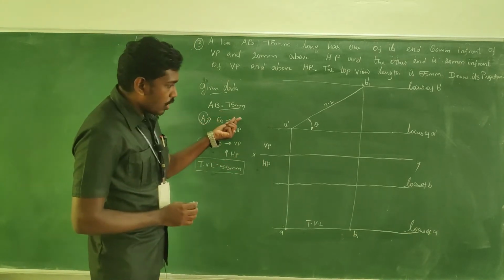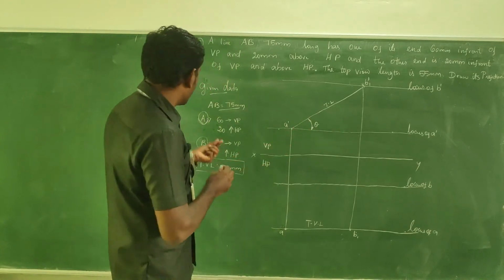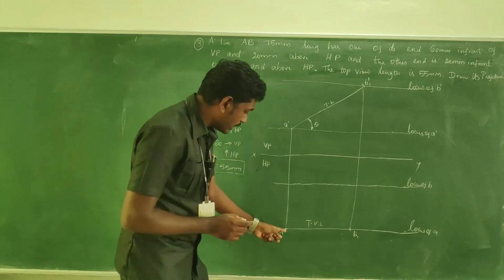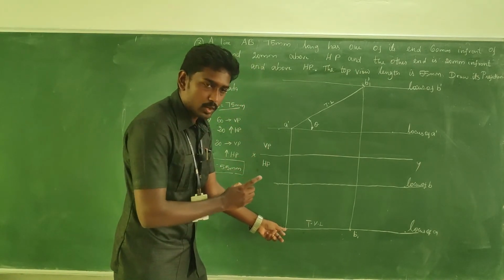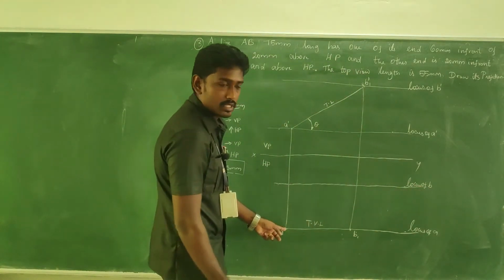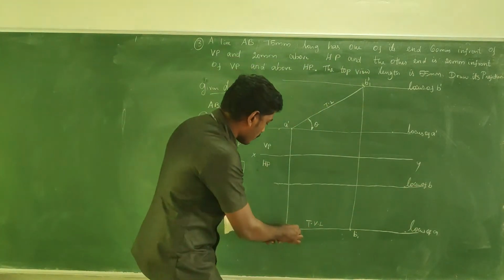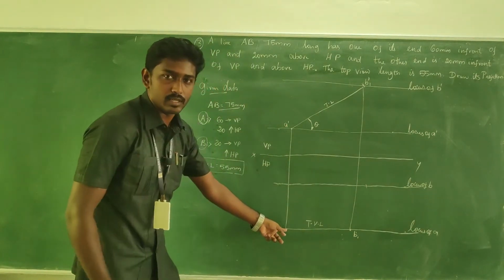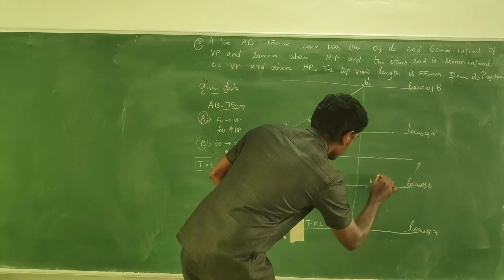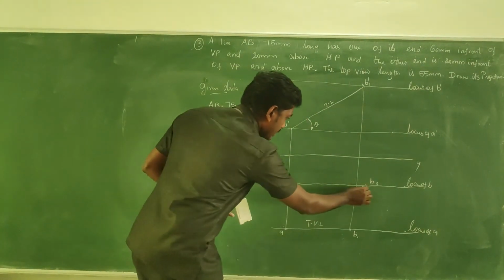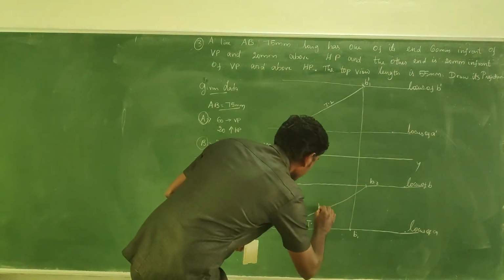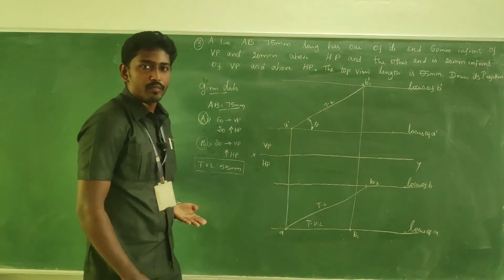Fine. Now in order to take the true length in the top view, take the measurement of 75 mm in your compass and keep the point as A. This is one of the ends in the top view. Another end is B, right? So search for the locus of B. Here it is present. So go for the cut mark with the measurement. This makes the point B2. If you connect a line B2 and A, it becomes your true length in the top view.